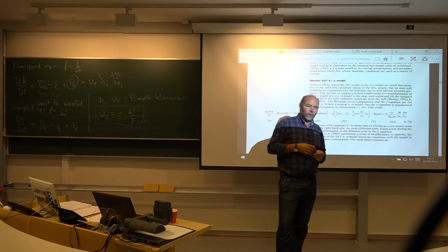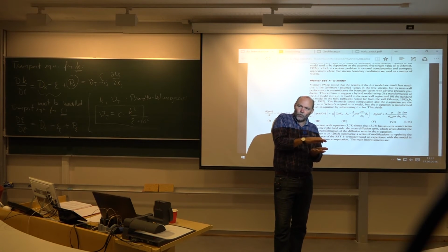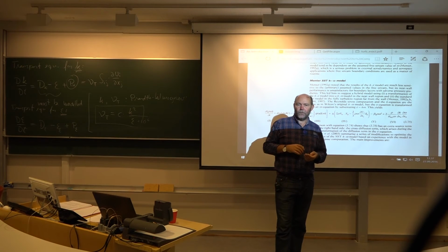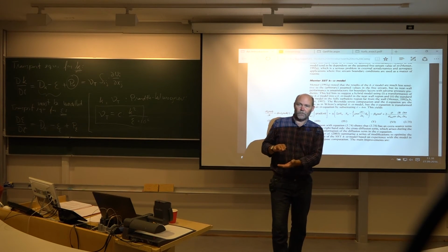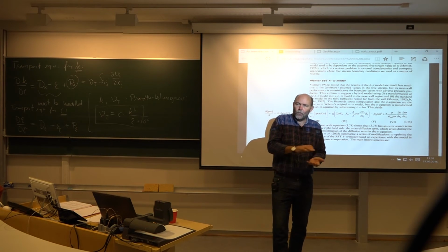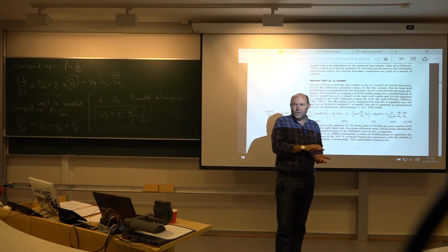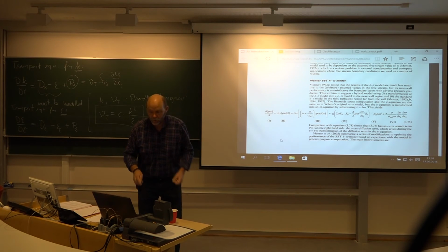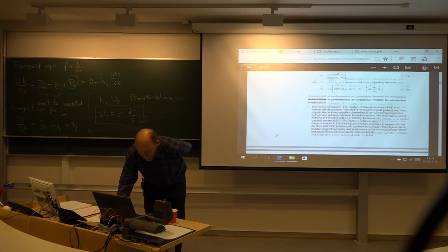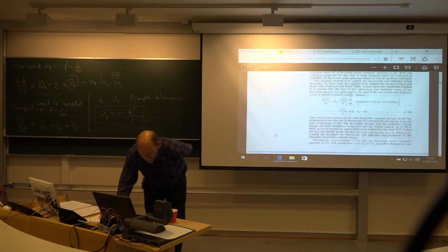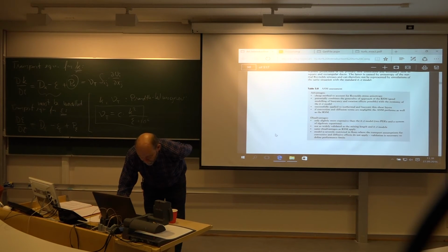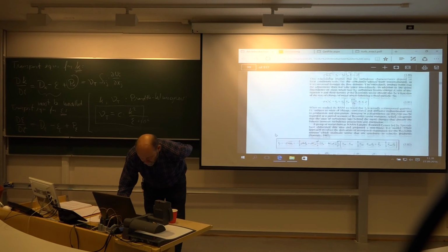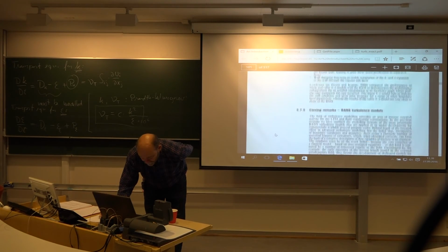There is an issue with resolving the boundary layer close to walls. That is a headache which we are going to address then on Thursday morning, because that's important. And also how this is done in OpenFOAM. Sometimes you have to resolve it, expensive. Sometimes you actually have to avoid it. That's actually very nice. We'll see also this in exercise 4. So we'll come back to this issue because it's important. What I wanted to find was this nice list. ASM. Should be more lists here. K epsilon.